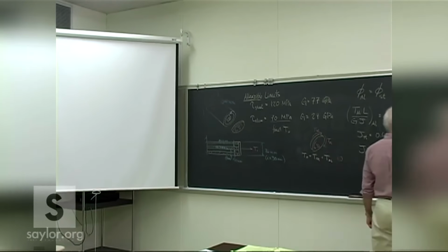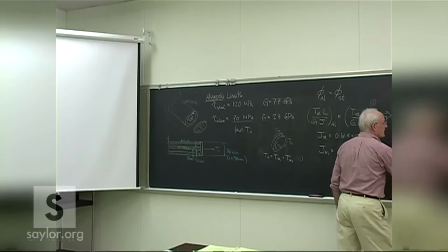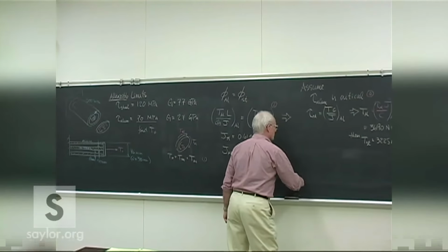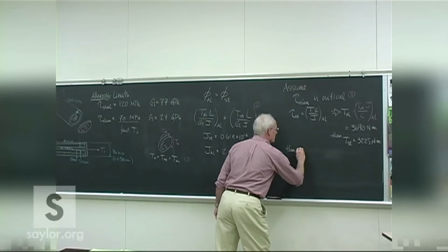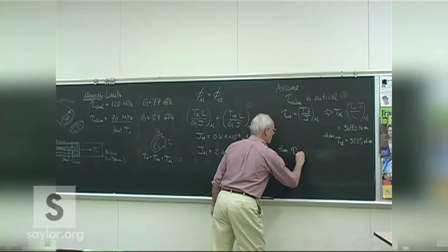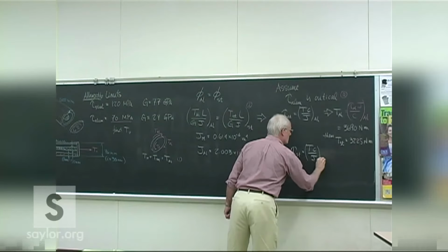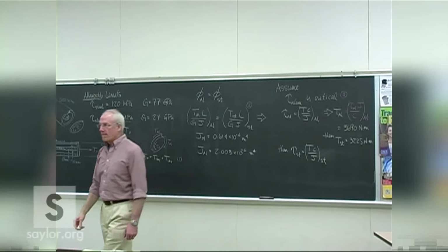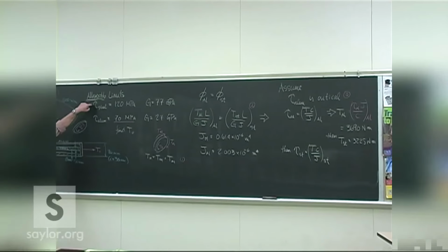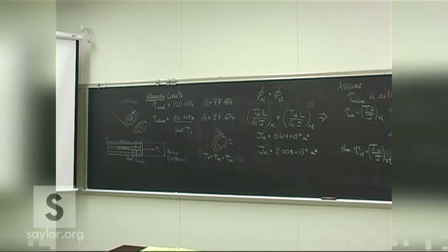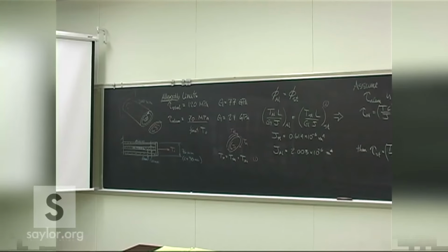All right, once you find the torsion in the steel, then you can in the same way find the shear stress in the steel. Now that we've got that, compare that number to the limit on the steel. Get that far, Travis? Oh, that's not a decimal point, it's going to be up there. Yeah, so the assumption is wrong.